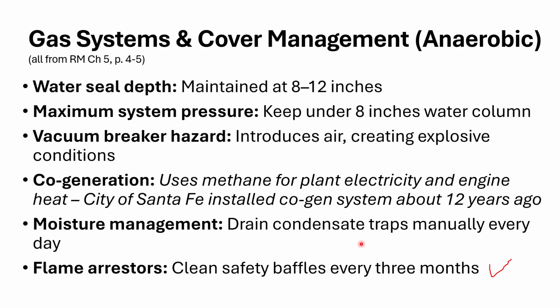The condensate trap, it's got to be drained manually every single day. And water seal depth, 8 to 12 inches. Maximum system pressure, an 8-inch water column, just like we talked about. Important stuff to remember. Okay.